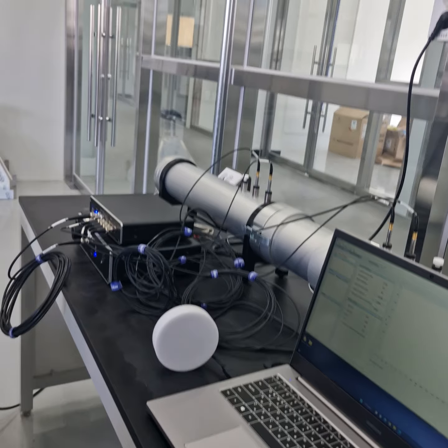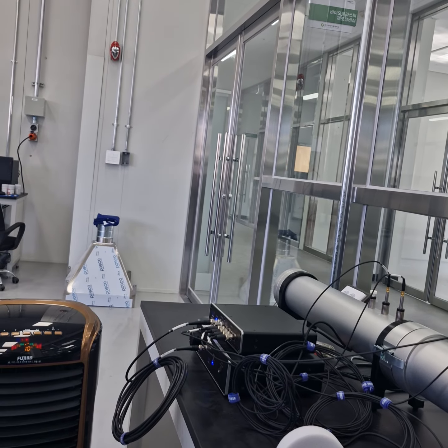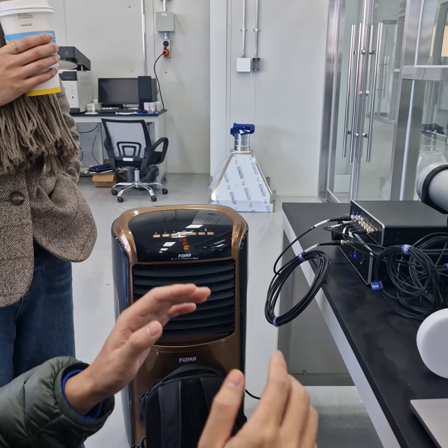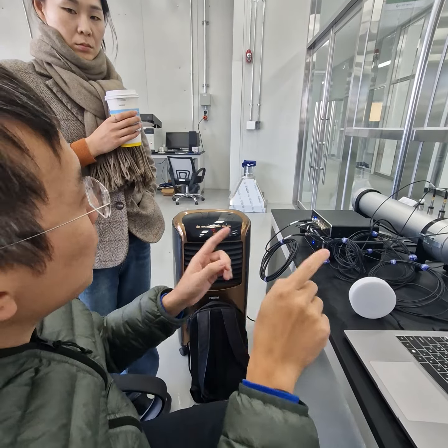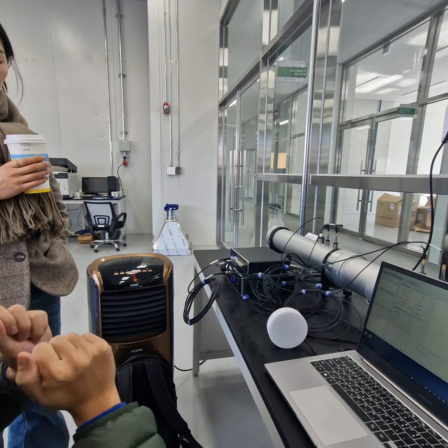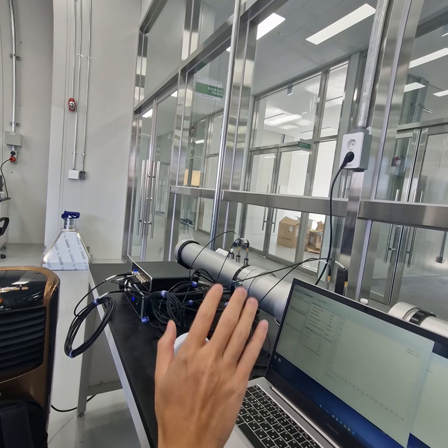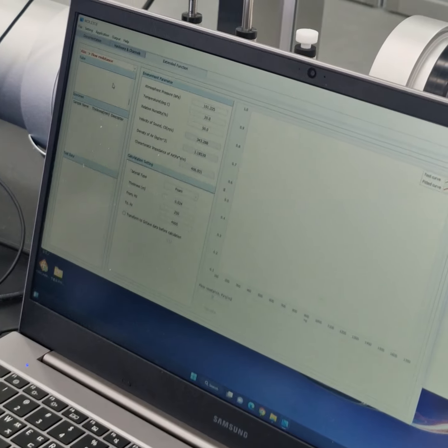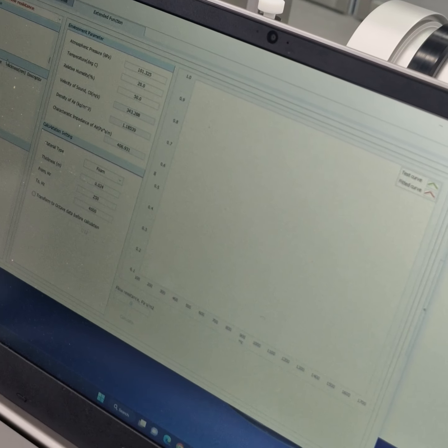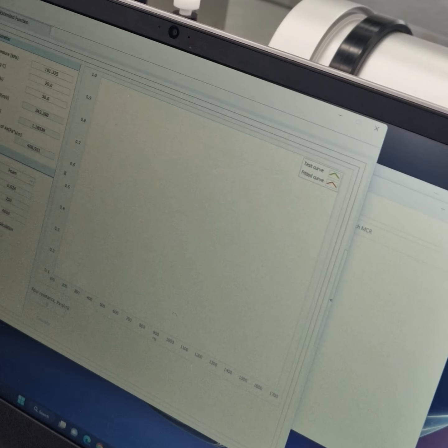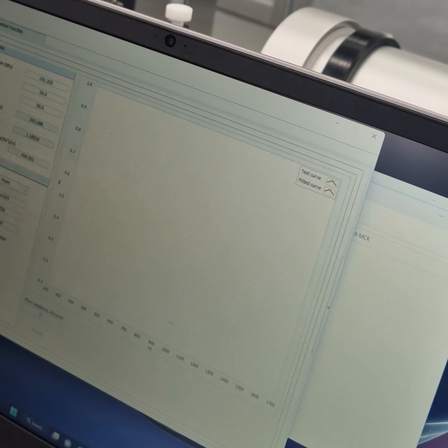Back in old times, scientists developed empirical models to calculate the relationship between airflow resistivity and sound absorption. In this function, we can use the tested sound absorption to predict the flow resistivity. But what we tested is the transmission loss, so the data is not in here.